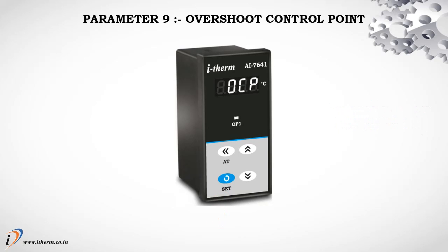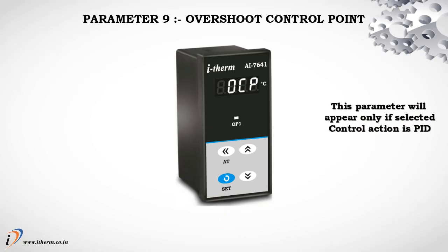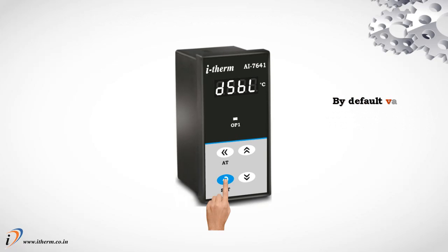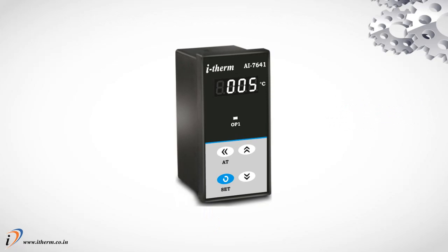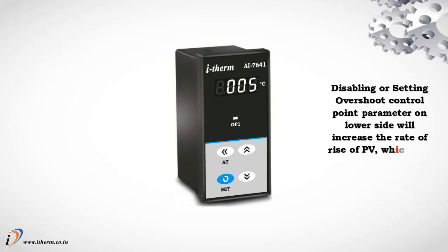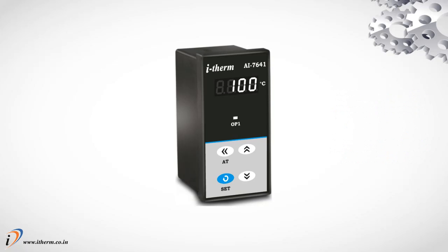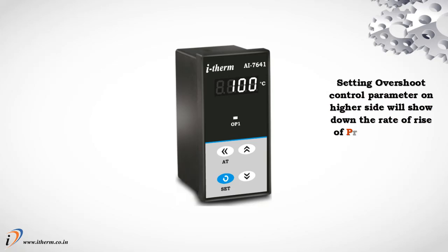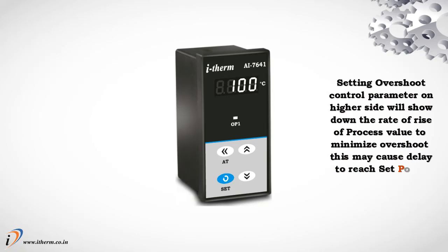Parameter 9, overshoot control point. This parameter will appear only if the selected control action is PID. By default, the value of overshoot control point is disable. Disabling or setting the overshoot control point parameter on the lower side will increase the rate of rise of process value, which may cause overshoot. Setting the overshoot control parameter on the higher side will slow down the rate of rise of process value to minimize overshoot. This may cause delay to reach the set point.